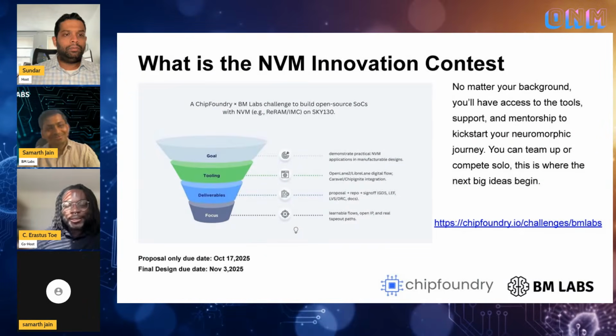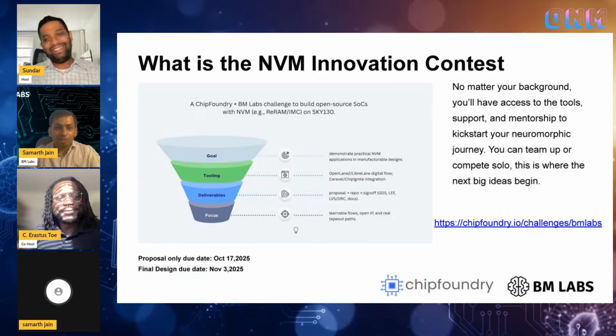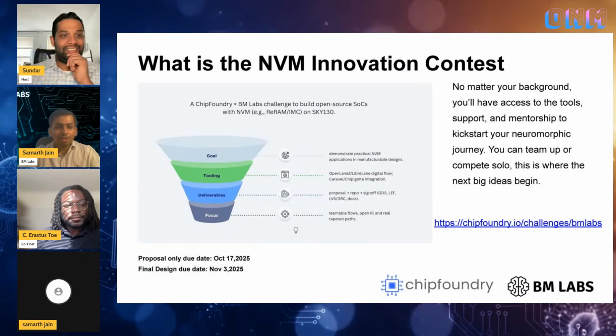So let's just assume that someone wants to get into developing neuromorphic hardware. They really have no prior experience apart from basic and fundamental research. How do you get into developing neuromorphic hardware? Yeah. So I think what you would need is just simple Verilog writing experience. And if you don't have it, I think you can use GPT for sure. Once you have your Verilog code ready, just use CocoTB to verify your timing, right?